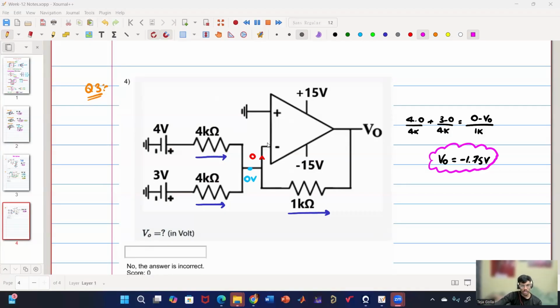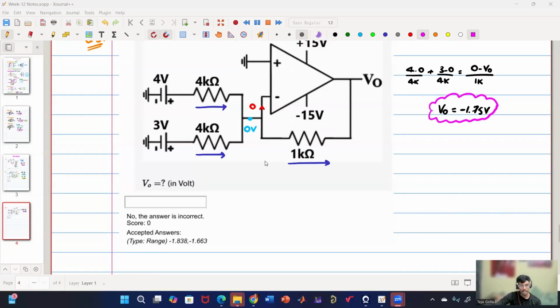But in this course, all the op-amps are connected in negative feedback fashion, so you can blindly consider these as virtually short, because that is in the syllabus of this course. But you will know in the future that this virtual short will only happen when there is an ideal op-amp as well as negative feedback. You will get to know that later, but it's okay. For this course, you can blindly consider it.